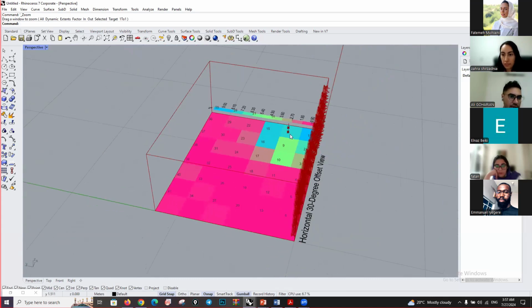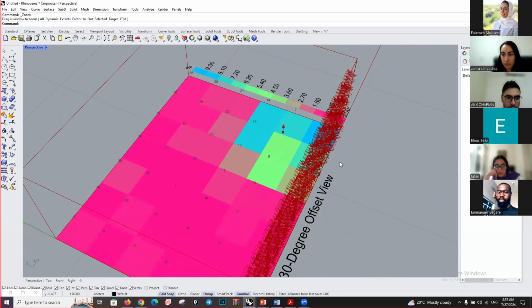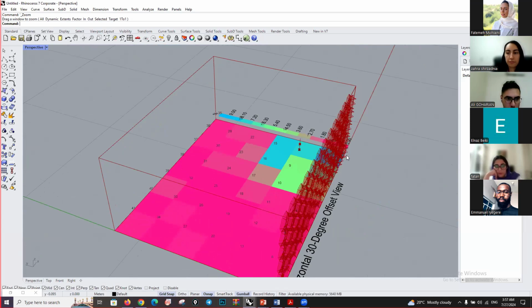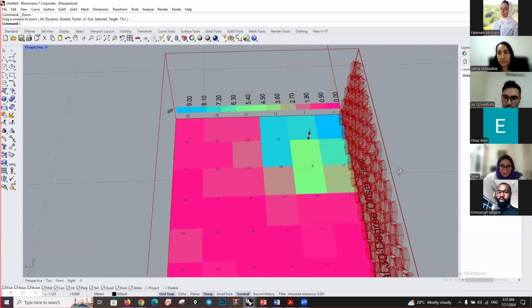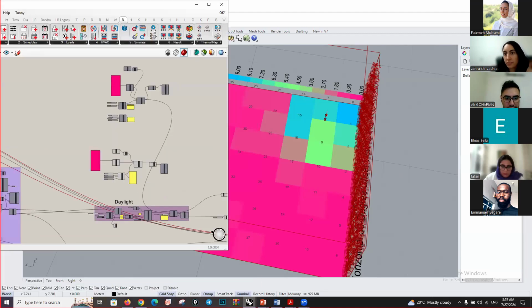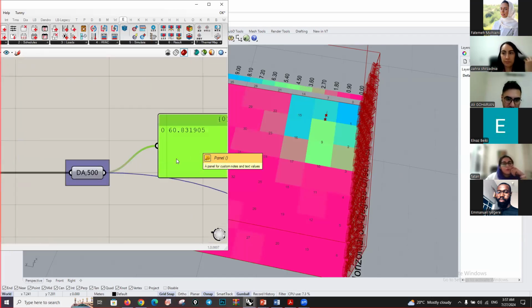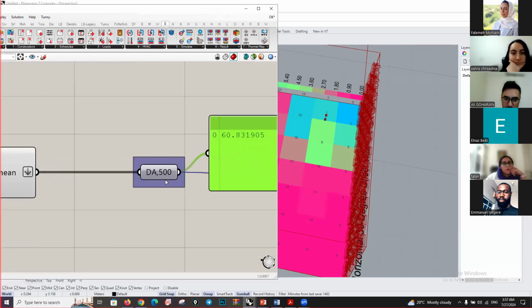but it depends on your project, your problem actually. It is my opinion. And actually, I decided to make the adaptive facade sensitive by this test point. But for you it may be varied. And after that, we have all test points, and for daylight efficiency, I consider the average of daylight efficiency as follows. As you can see in this panel, this is my daylight efficiency, the daylight autonomy upper than 500 lux.